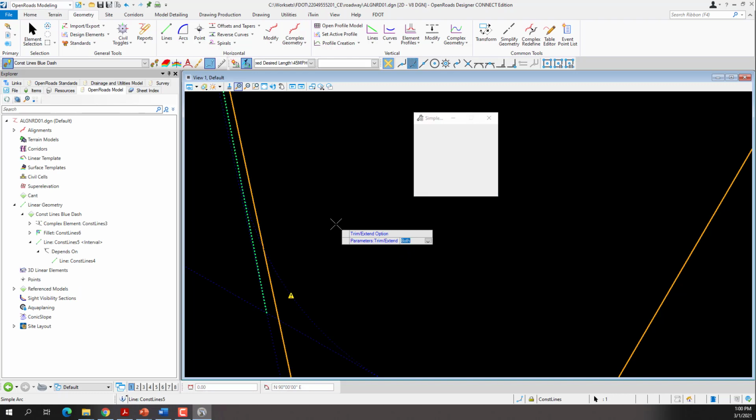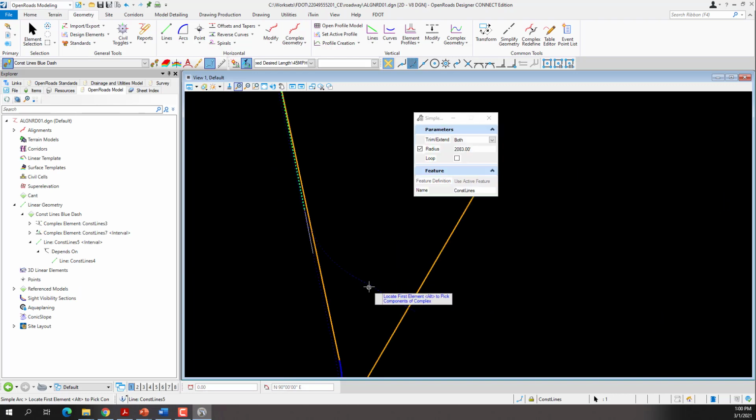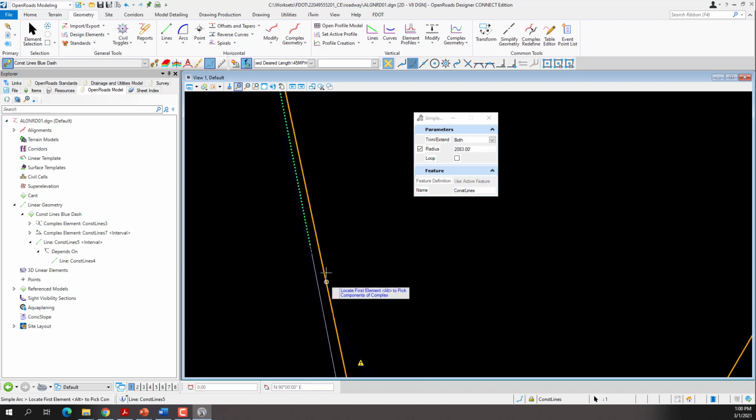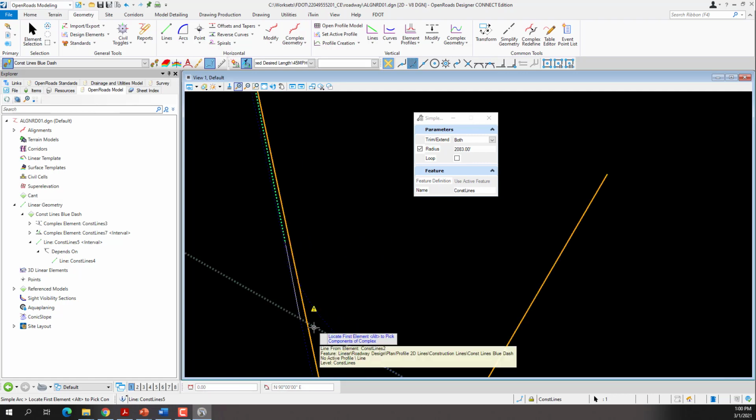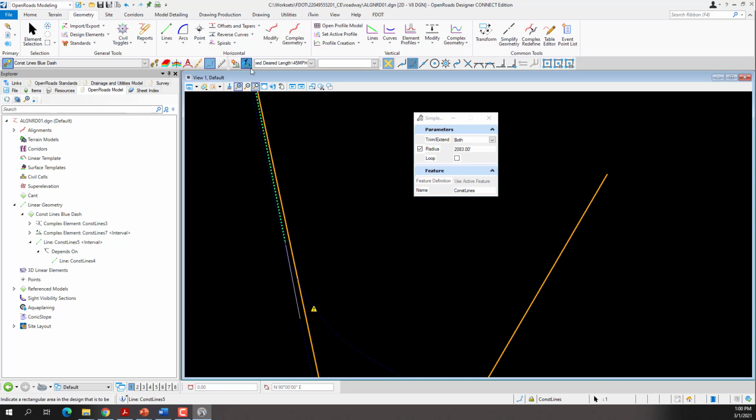And you'll see that it trimmed the arcs and created more intervals and more information. Or it trimmed back because it's following the command. So it created another interval for that arc between construction line 5 and construction line 2. You'll notice when we place that, since we have a design standard, a length, we have that applied, we have a little glyph or a little message that we need to look at and see. That Civil Message Center is under the General Tools. Under Standards, we can bring up the Civil Message Center.